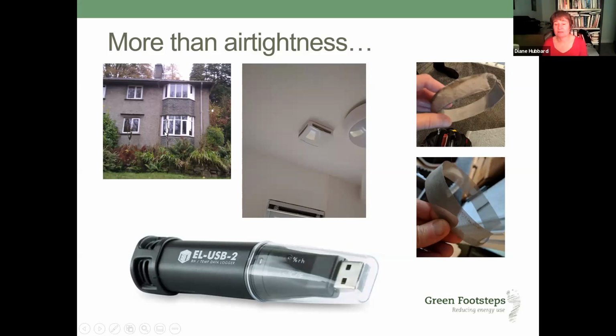It's suspended floors, quite a lot of widespread issues. The bays on the front are just timber frame, slate hung. There was loads coming in through there. Post refurb, it came at about 4.5, I think, in terms of air permeability.